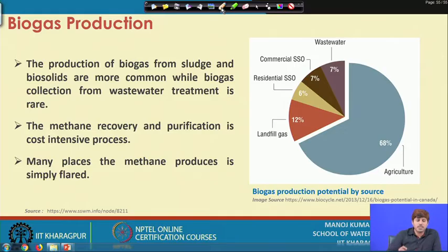Now, with the sludge or the solid waste, the concentrated waste, the amount of organic matter present is high, and the corresponding production of methane is sustainable, meaning a significantly high quantity of methane can be produced. Then it makes some sense to install certain kinds of systems to collect, purify if needed, treat, and transport the gas.